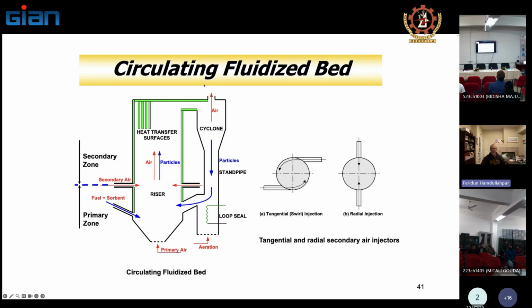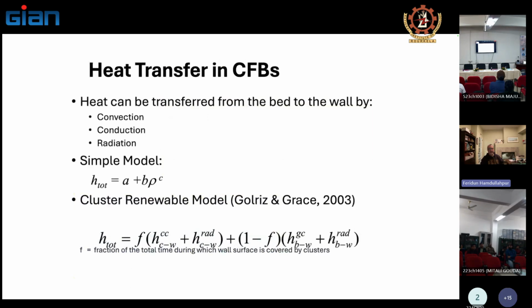A lot of when gas sampling was being made here, right around here, they were measuring a lot of carbon monoxide, presence of carbon monoxide. And the reason for that was that it showed that all the fuel was not reacting. It should have been much less carbon monoxide, a lot of carbon dioxide, whereas the ratio was much higher here. That necessitated blowing more air here, providing more air, therefore increasing the excess air ratio, but more importantly, to promote that mixing here.